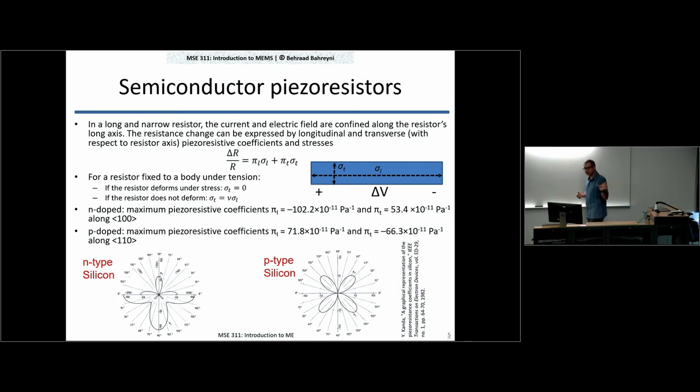So the change in resistance due to 1 megapascal of pressure is just 0.1%. It may seem small, but it turns out that it's actually a very easy to measure value. So that kind of sensitivity is actually fairly high. And when we look at other transduction mechanisms, you see that piezoresistive sensing is usually your go-to method if available.